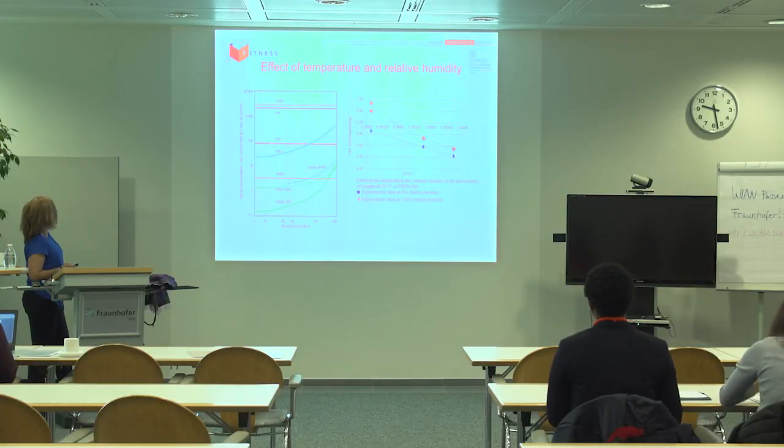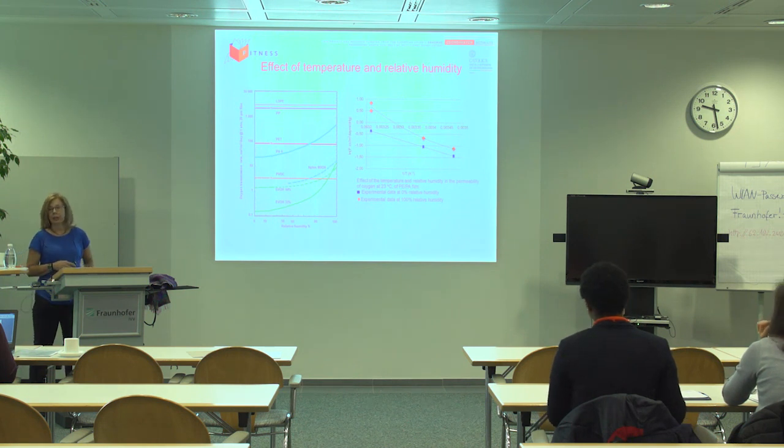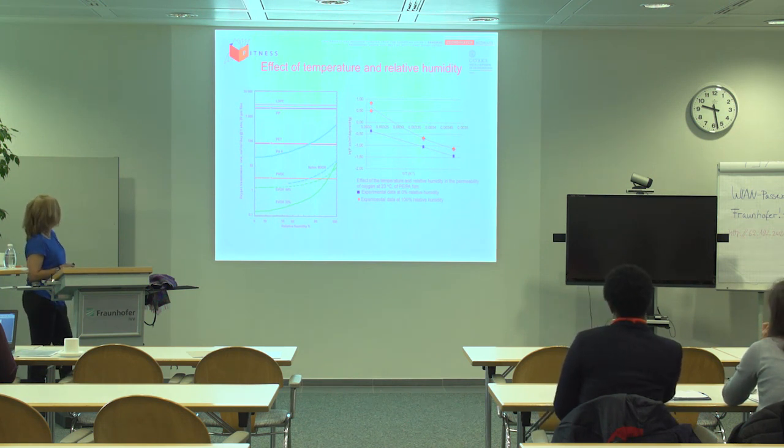Here we see the effect of temperature and relative humidity on the oxygen transmission rate for a film of 20 microns. And we have here in this axis the relative humidity.